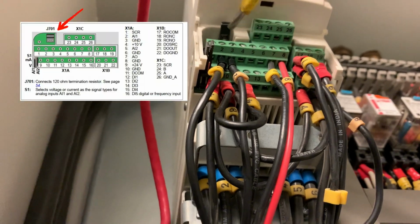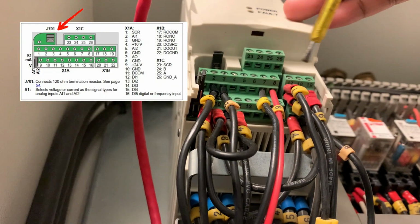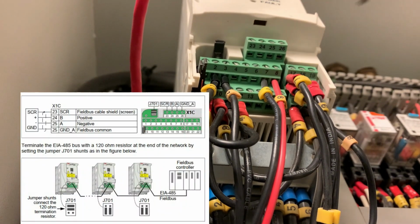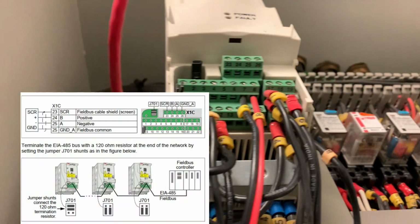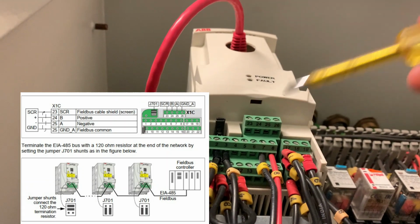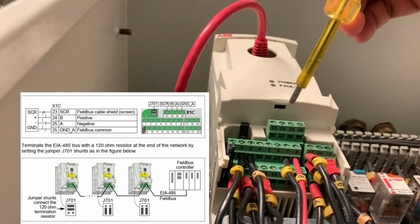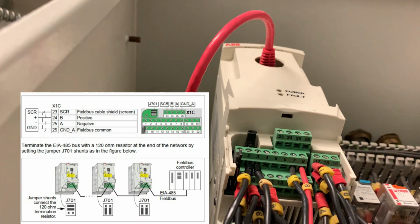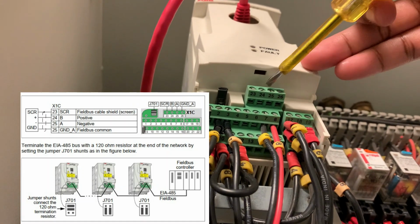Okay, and these two are the termination resistor when you are using Modbus, because these terminals 23, 24, 25 and 26, these 4 terminals, are used when you have a Modbus RS485 communication cable. Then you have to connect this terminal with the other VFD, and then at last you have to connect it to the PLC or the BMS system, when you want to use a Modbus protocol or RS485 protocol.